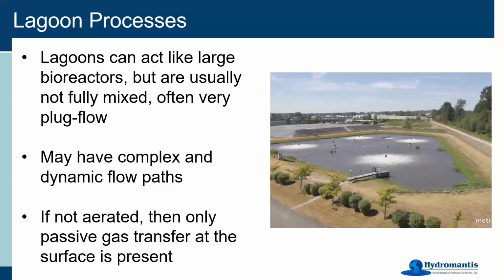As I mentioned, they can act like very large bioreactors, but they're very much not fully mixed. They're not one giant CSTR like you might imagine. They're very often plug flow in nature and can have very complex and very dynamic flow paths through the system from the influent to the effluent.